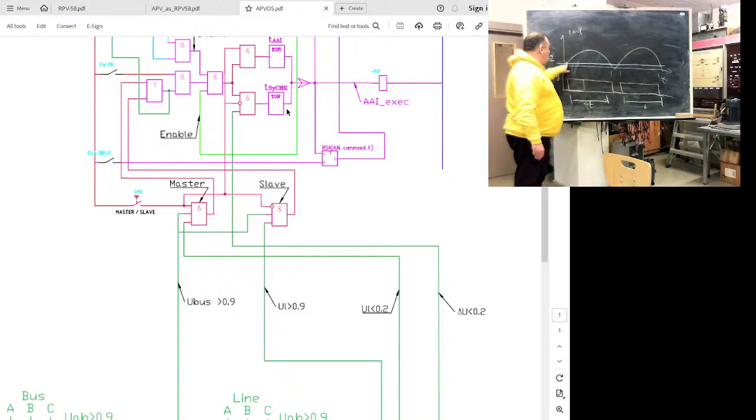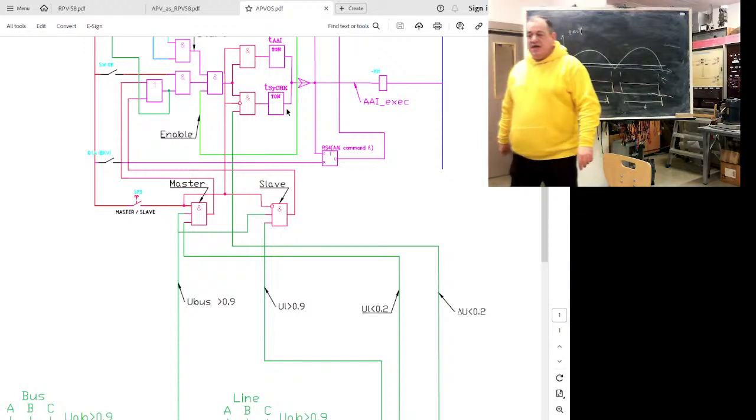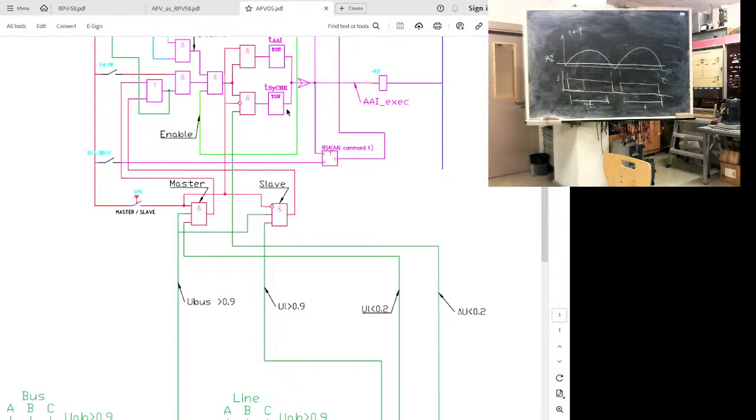The time of this part of the arc is compared to the predefined time of the synchro check timer. It's the way to check the frequency difference. It's done like this for a reason: it is quite hard to measure frequency precisely in a short period of time, so checking the voltage difference works better.